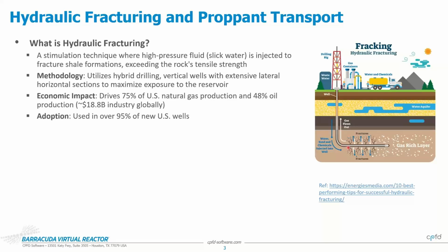This fluid is not just regular water; it's usually mixed with some sort of polymer to increase its viscosity and also make it a shear thinning fluid. Once you pump it down and create perforations through a perforating gun into the casing and the formation, this high pressure fluid fractures the formation and creates these fractures.